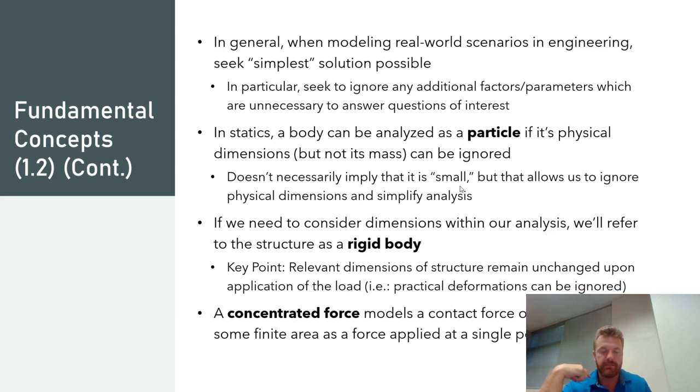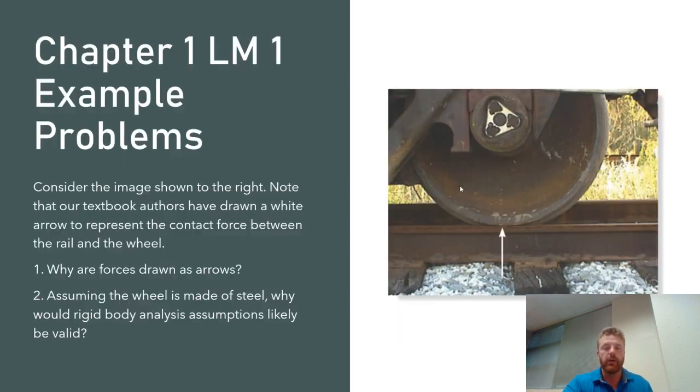So concentrated force, what I mean by that, well, you can't really see my coffee cup sitting on my laptop here, but at which points on the bottom of that coffee cup is my laptop exerting a force on the mug in order to counterbalance its weight? Is it right in the middle? Is it right on the edge? Well, physically, that contact is distributed over some surface area. So whenever you have a contact force that's distributed over a finite area, but you're going to model it as just being applied at a single point, the book will refer to that as a concentrated force.